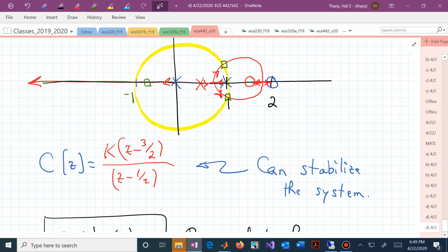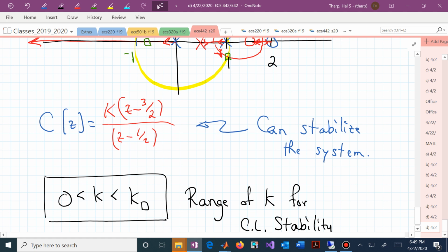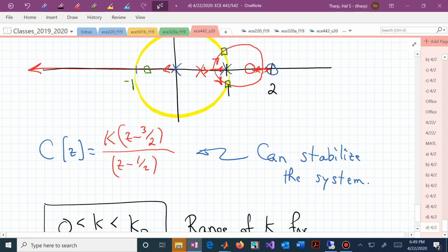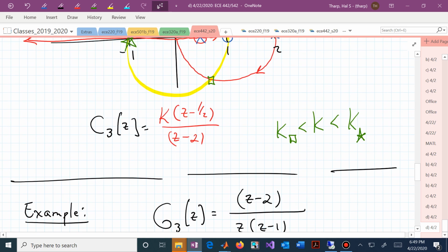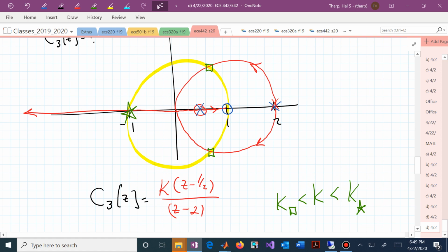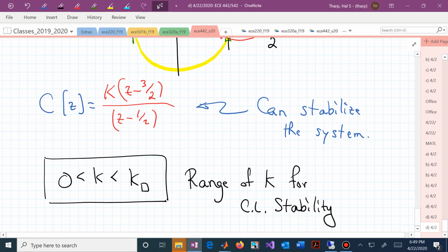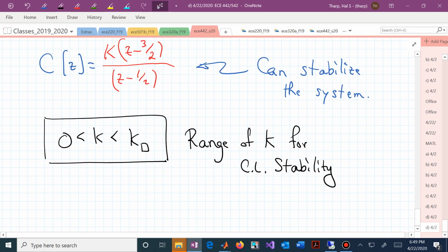That now, I hope, gives you a little bit of intuition into how you might stabilize with general controllers. Here we now had a non-minimum phase controller. It was stable, but we needed that in order to stabilize this non-minimum phase system. We also before had to introduce unstable controllers to stabilize an unstable plant. That will hopefully get you some intuition into how to design general controllers for unstable systems and non-minimum phase systems.